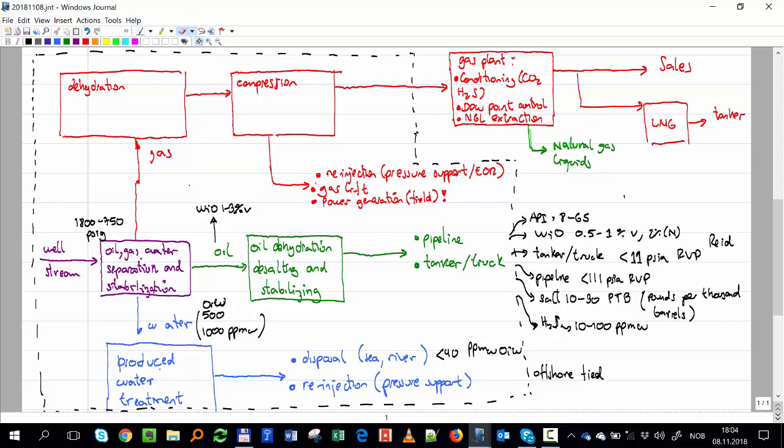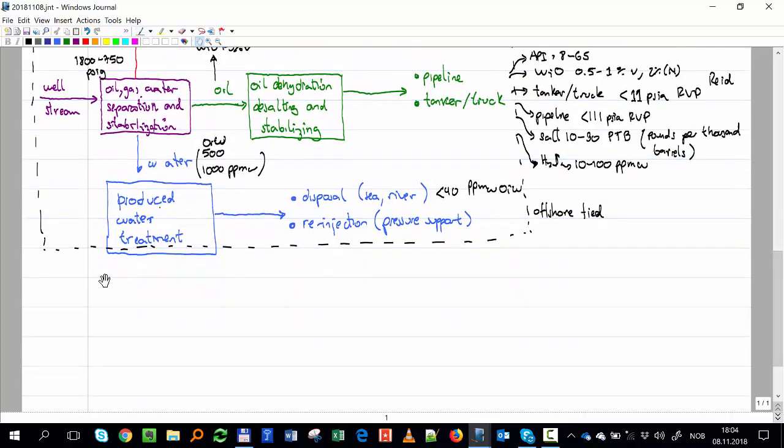Here I just want to emphasize, sometimes it's very difficult to get this number. So that means you cannot process that much water that comes here. Remember the discussion we had yesterday. With time, usually the rate of water, or the water cut versus time, is increasing. So when you are at the late stage in the field, these facilities will need to take a lot of water. And if for some reason the time is not enough to get to this requirement, you have to reduce the rate.